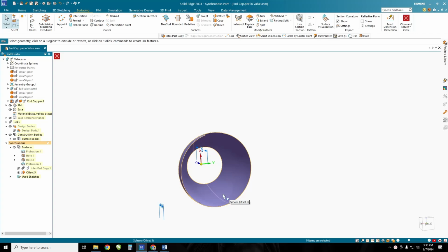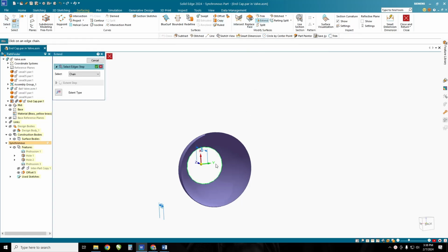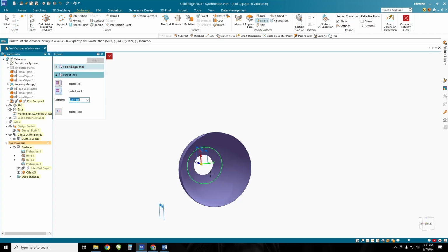and we're going to use our extend tool to move the inside of this circle in. So let's go up here to extend. Here we go, extend. I'm going to select this inside here, right click to check, and you'll see I get to move this in. We just want to make sure that we move it in plenty so that it for sure is going to deal with that hole.